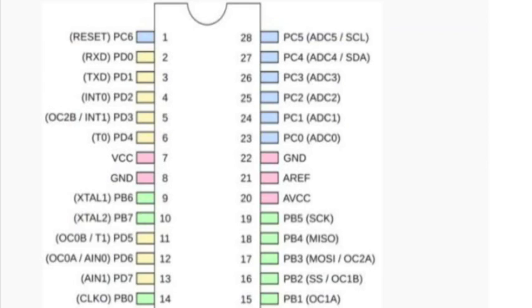So there's 3 timers on this chip: 0, 1, and 2. And so they're OC 0 something, OC 1 something. And then there's usually 2 PWM pins per timer. So it's OC 0A, OC 0B, et cetera. And so you could see how they're scattered all over the chip, largely not overlapping each other.